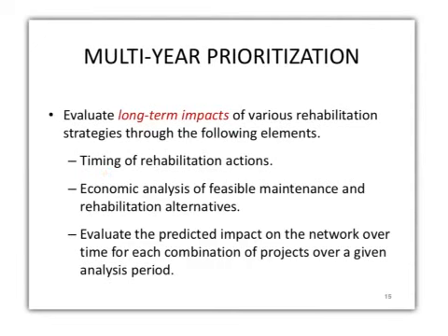Sometimes if the road is really deteriorated and we are just trying to do some minimal maintenance, that's not going to help. Or vice versa, if you have a very good road, you don't need to do a 2-inch or 3-inch overlay. The minimal amount of rehabilitation would be enough.